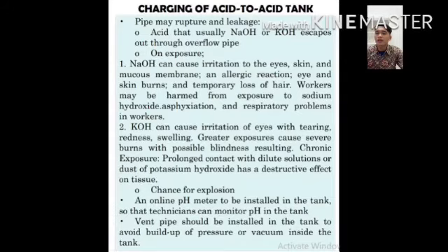Thus, potassium hydroxide has a destructive effect on tissue. There is a chance of explosion. An online pH meter should be installed in the tank so that the technician can monitor the pH in the tank. A vent should be installed in the tank to avoid build-up of pressure or vacuum inside the tank.